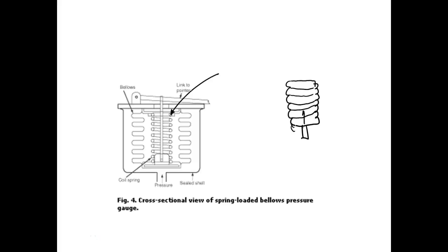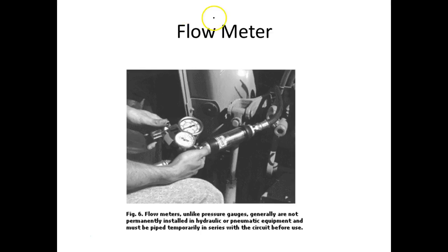If you ever go into a grocery store that has one of these rotating scales over in the fruit section, it's got that basket, and people go in there and measure the fruit. That's usually the calibrated spring. So you try to stretch that thing out, and the more you stretch it out, the more force it creates, right? And then when the force equalizes, that's where the reading comes. So we have this thing on a calibrated spring, so when it expands, it'll expand a certain amount until the pressure equalizes. So this is another method that we can measure pressure.